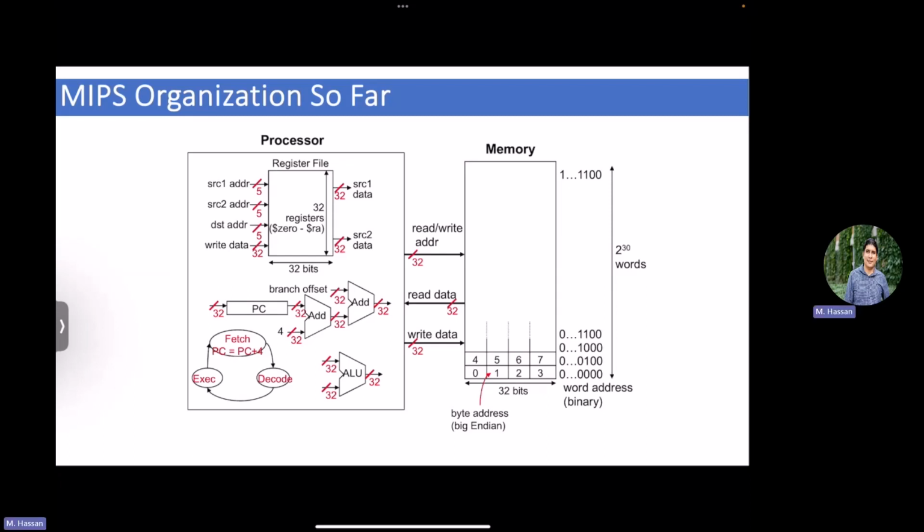But then if you ended up having a branch and this branch is taken, which means you need to jump, in that case, instead of adding the 4, you in fact need to add also the label, the offset that you need to jump to. From where do I get that offset? How to obtain that value? From the instruction itself, like we just said 5 minutes ago, right? A conditional branch already has a 16-bit offset that we simply can add to the program counter to jump to the new instruction, right? And we already had a discussion: what if I want to jump to a further place? This is not enough. Then I translate this into an absolute jump, right? And then I basically have a 24-bit offset.